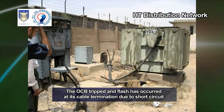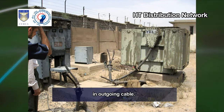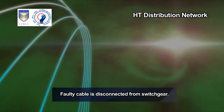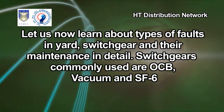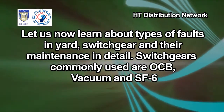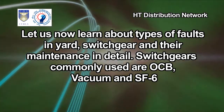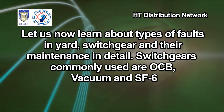The OCB tripped and flash has occurred at its cable termination due to short circuit in outgoing cable. Faulty cable is disconnected from switchgear. Let us now learn about types of faults in yard, switchgear and their maintenance in detail. Switchgears commonly used are OCB, vacuum and SF6.